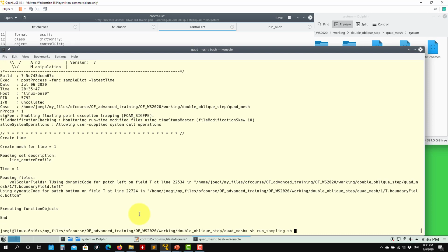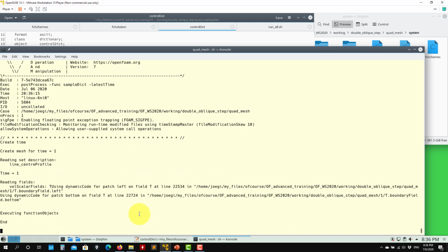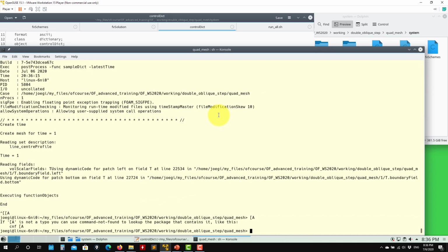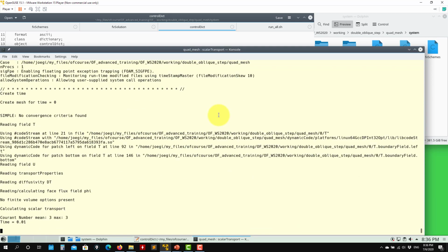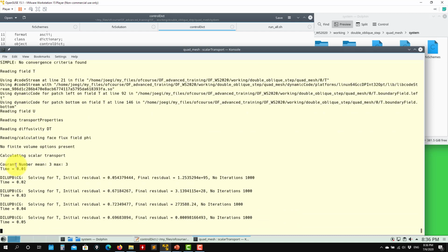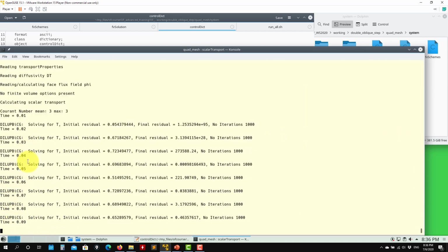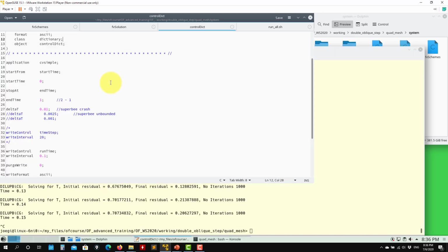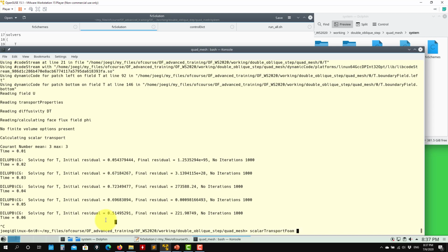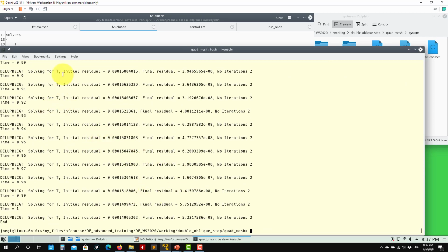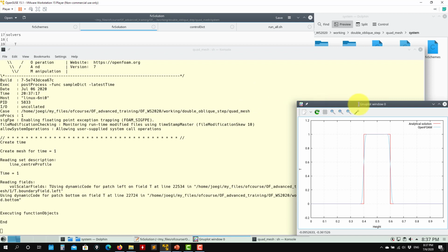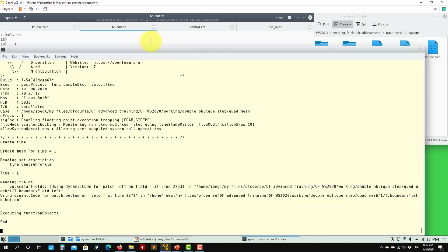Usually in unsteady problems, it can also be a good solution. If you have good numerics and you still have divergence, then you can focus on the time step or on the relaxation factors. In this case, I went back and reduced the time step, but see that we still have the problem. So let me stop it here and add the relaxation factors. See that in this case the relaxation factors actually have a stabilizing effect. So we do the sampling and we get it right there.